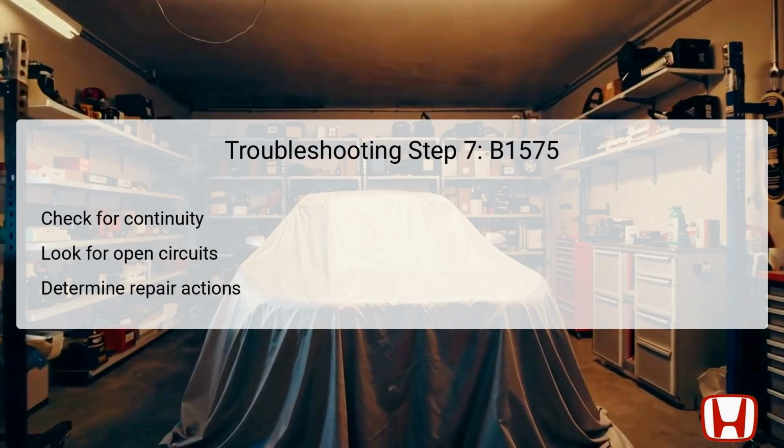In the final troubleshooting step, checking for continuity will reveal critical information about the fault's cause. If continuity is present, this confirms that the wires are intact and functioning correctly up to that point. However, if there is no continuity, it indicates that there is either an open circuit or high resistance affecting the wiring. This finding may lead to the conclusion that the passenger's microcomputer interface unit, MICU, is faulty, which would require replacement of the fuse/relay box.